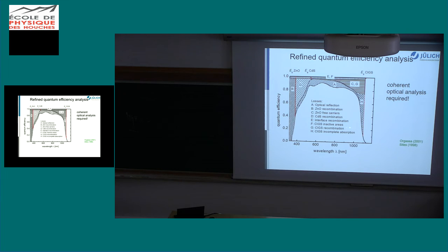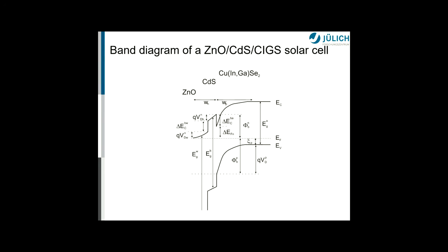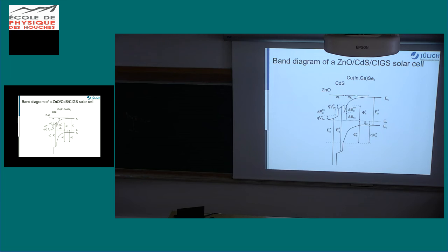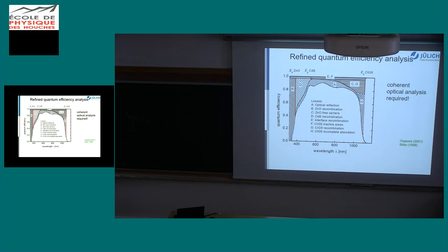And then there's interface recombination, because any electron that comes from the absorber must go over that interface, and if there is a certain probability to recombine at that point, regardless of where this electron comes from, regardless of which energy photon it has been made from, it's just not there.